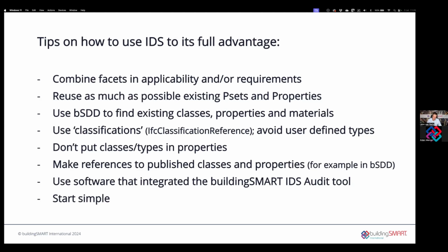Also, classes in the BSDD, please use these classes inside IDS, and then they will end up as classification reference in IFC. This is a much more powerful and flexible way to add further IFC specializations instead of using user-defined types, which is really not recommended.